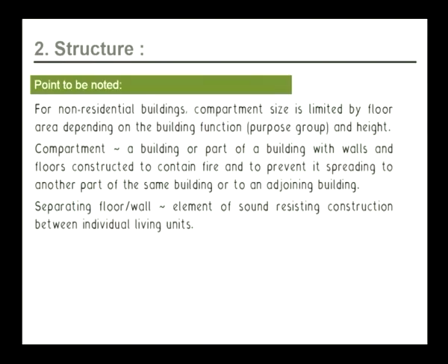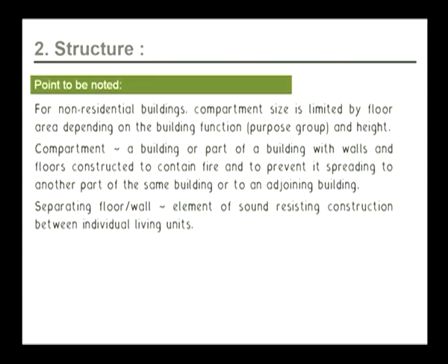Point to be noted: for non-residential buildings, a compartment size is limited by floor area depending on building function or purpose group and height. Compartment is defined as a building or part of a building with walls and floors constructed to contain fire and to prevent it from spreading from one part to another part of the same building or to an adjacent building. That is why compartmentalization is so important in any structure. Separating floors or walls are elements of sound resisting construction between individual living units. So, compartmentalization provides us sound resistance between individual living units and the adjacent living units.